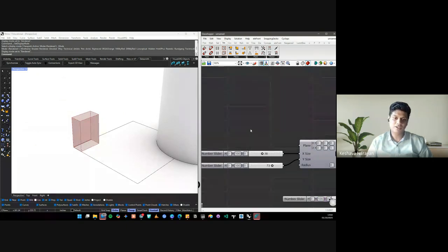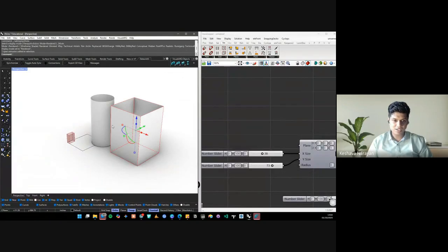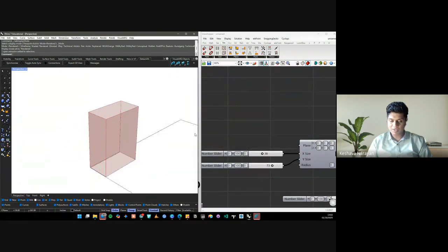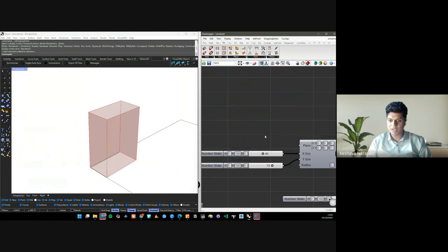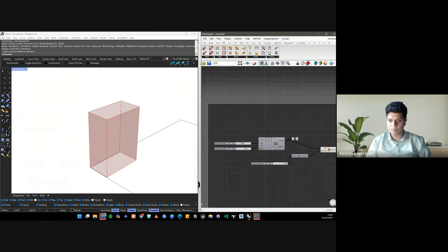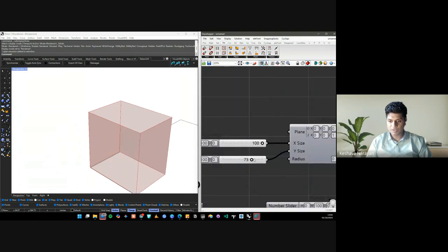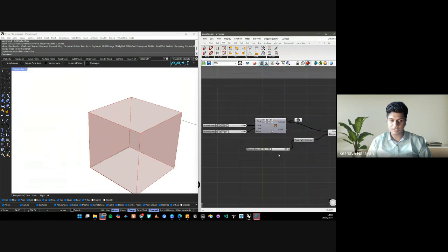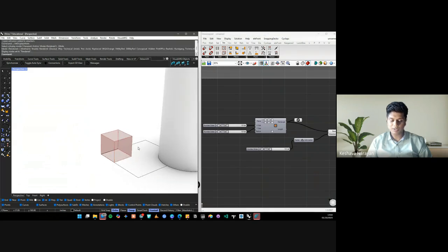This is a parametric model. What we created earlier was a static model, because if you change this, the geometry changes. But here, what we have done is created something called a dynamic model, where you can change any of the information that you want, but still it retains its information. You can also go back and say, now I want everything to be 100 mm, 100 mm, and 100 mm. I can just increase everything. Since the length, breadth, and height are all equal, now what we've created is a cube.